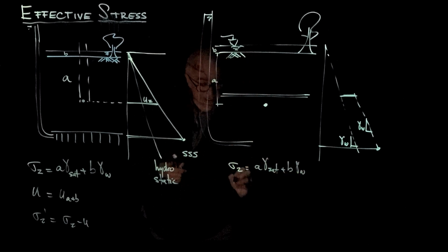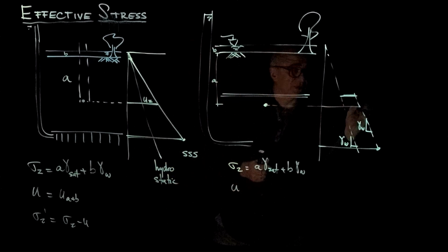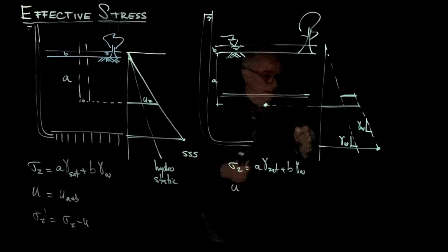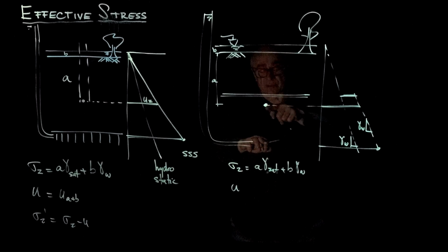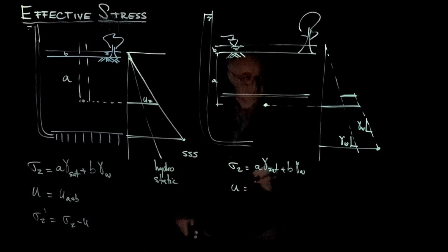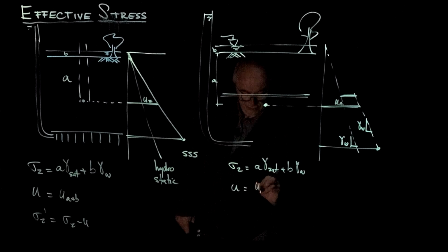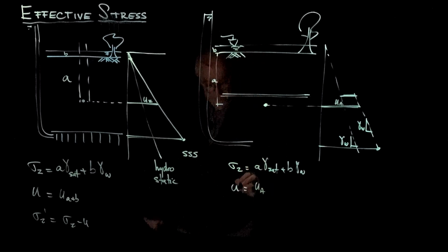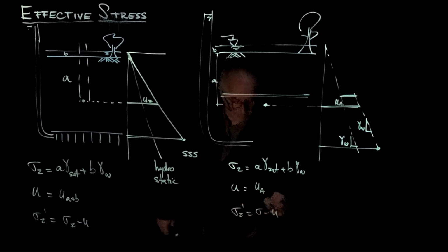Now, the pressure at the point is the pressure that you have to pick up from this diagram. So it will be the pressure at the bottom, where the Artesian pressure is, minus gamma water times the height with respect to the Artesian elevation. That will be the pressure that we're talking about, the pressure at point A, and so it's U at point A. And the subtraction is Terzaghi's effective stress, as always, sigma minus U.